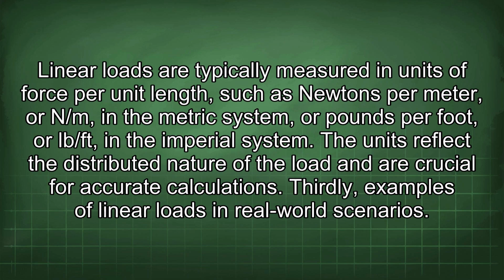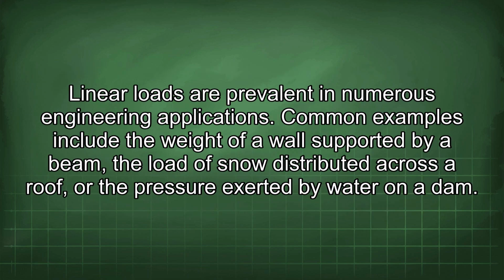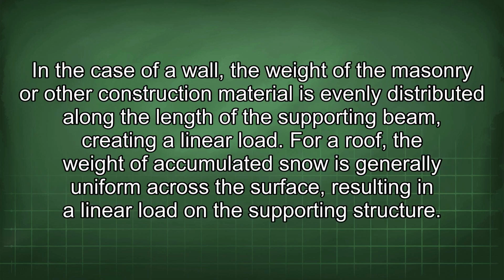Thirdly, examples of linear loads in real-world scenarios. Linear loads are prevalent in numerous engineering applications. Common examples include the weight of a wall supported by a beam, the load of snow distributed across a roof, or the pressure exerted by water on a dam. In the case of a wall, the weight of the masonry or other construction material is evenly distributed along the length of the supporting beam, creating a linear load.